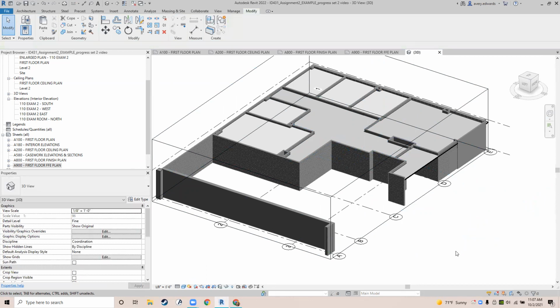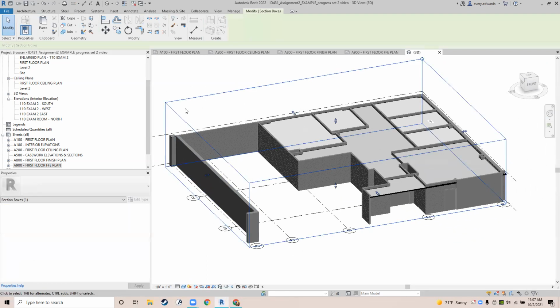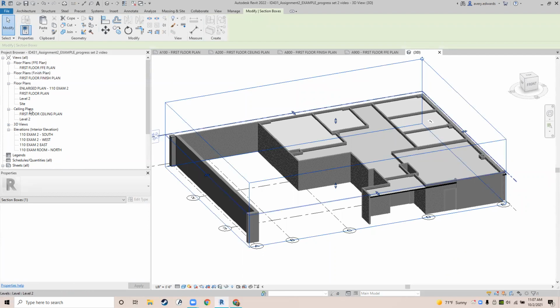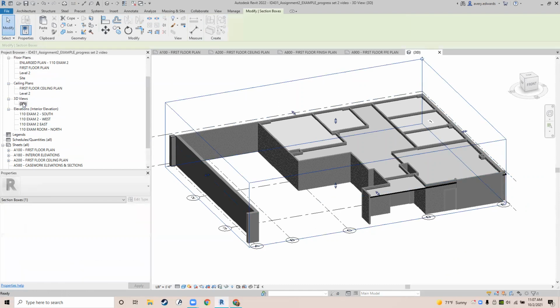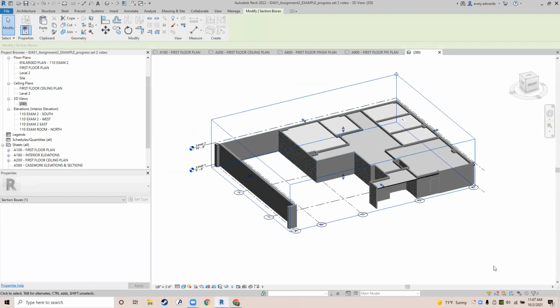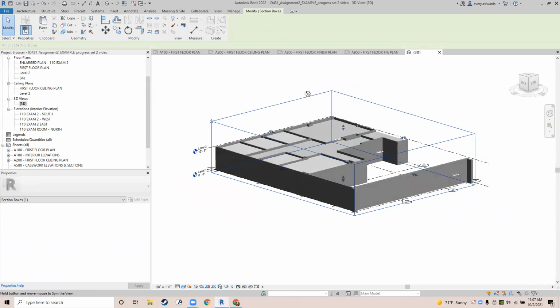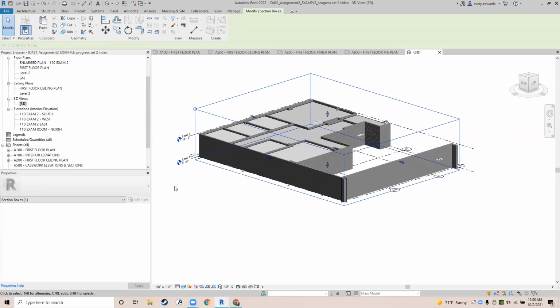Okay. And also, when you're using this selection box, it can be really convenient when you're trying to look at stuff like way down inside a floor in your building, because generally, if you go over here to the 3D view that Revit gives you automatically in your browser, it'll usually show you the whole building, and you don't want that, right? Sometimes you're trying to see inside this room, and it's so hard when you're on the outside of the building. So when I was in school, I used to just select big chunks of the building and hide them and unhide them. But then that's not good, because it's hard to unhide all of that, right? Sometimes there's still things you want to stay hidden. It's just a mess.